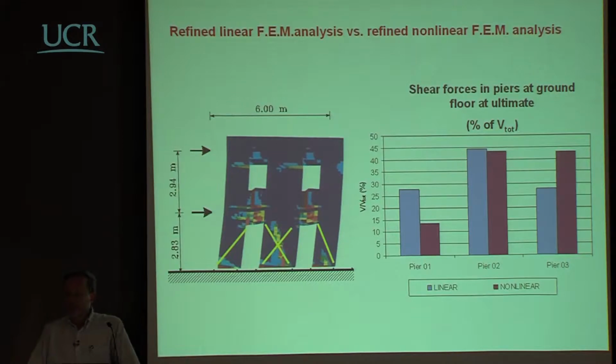Exactly like in the case of concrete walls, the differential axial force is directly related to the capacity of the lintels to transmit bending moment and shear. If there is no capacity to transmit bending moment and shear here and here, then this complex wall will react essentially as three separate walls, and the only resisting mechanism will be the bending moment capacity at the base of the wall.